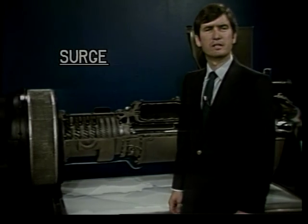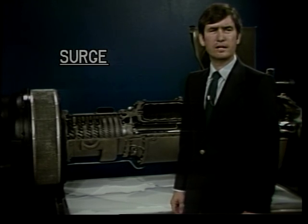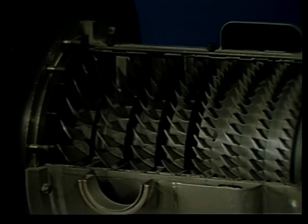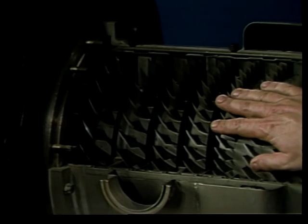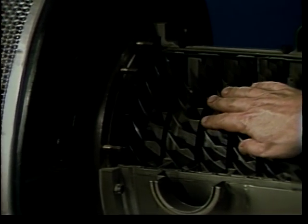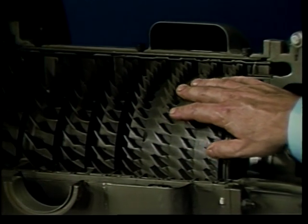Surge is a condition that can take place in the engine compressor at low engine speeds. It is caused by a blockage of air in the last stages of the compressor. The engine compressor is designed so that at operating speeds, all 8 stages pass on air equally at the same level of efficiency. At low speeds, however, during acceleration and deceleration, the forward stages are able to accept and pass on more airflow than the rear stages can handle.